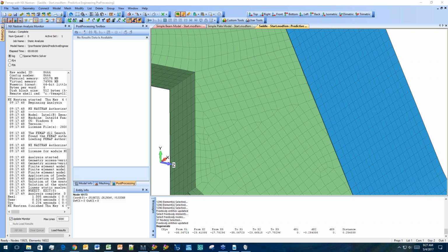Then you're going to use those stresses based on the weld type or weld category and find the corresponding SN curve. The other option, weld sizing, more of a design guide like Kyle covered. You're going to extract your forces, and then you're going to have these conservative hand calculations to give you weld sizing. If you skip this step and follow the stresses in your model, you could end up with something that is not conservative, like his little stoplight example there. So really, building the model and running the analysis are just the first steps in a bigger process.